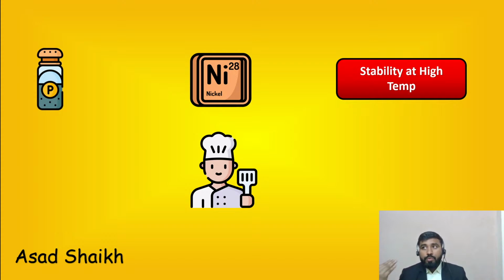But if you have an offshore application and the vendor gives you, for example, 0103, don't accept it, overall speaking. The other way around could be accepted depending on what type. If it's painting, yes, you can accept, but if it's exactly the material, I would say no, don't interchange them, because for refinery, sulfide stress cracking is something more severe for them. So 0103 addresses that in depth. So for sour service, I would say yes, definitely go for NACE. Your pipe spec will also specify mostly NACE, so from there also you get a clue that okay fine, it's a sour service, I need to specify NACE.